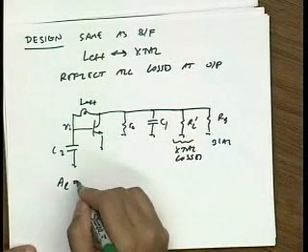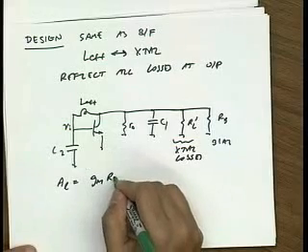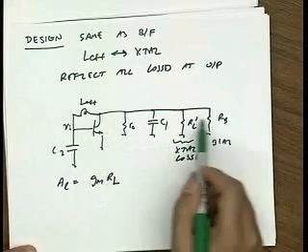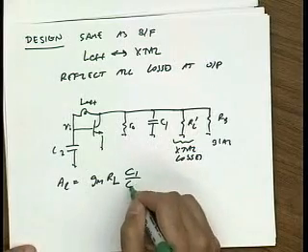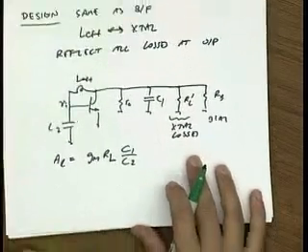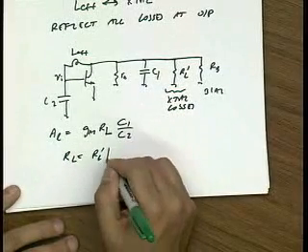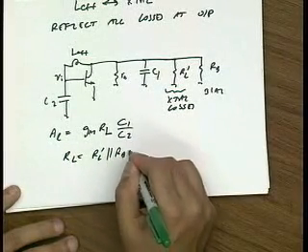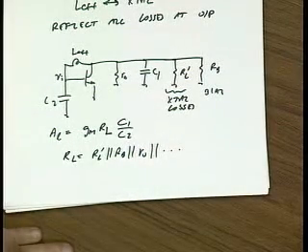And so the total loop gain is g_m of this transistor times R_L, which is a parallel combination of all these resistors, times the feedback factor divided by N, which is C_1 over C_2. And R_L is R_L prime in parallel with R_B, in parallel with R_O, and so on and so forth.